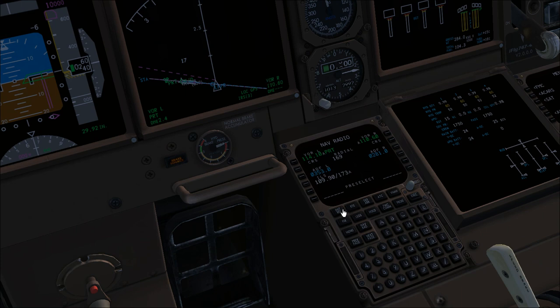There is also the possibility to check the position of the aircraft against the FMC calculated position. As you can see, as I said, actually only GPS is used for position. As you can see, FMC position, GPS indicated, and you have all the positions in position reference 3 out of 3. Now we can return to the takeoff page and continue with the preparation. We have finished the CDU preflight.